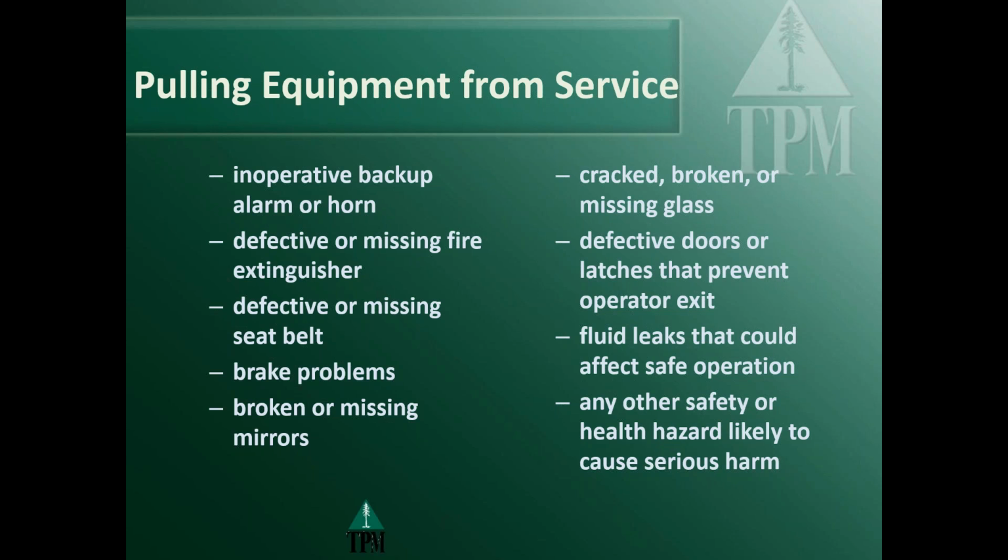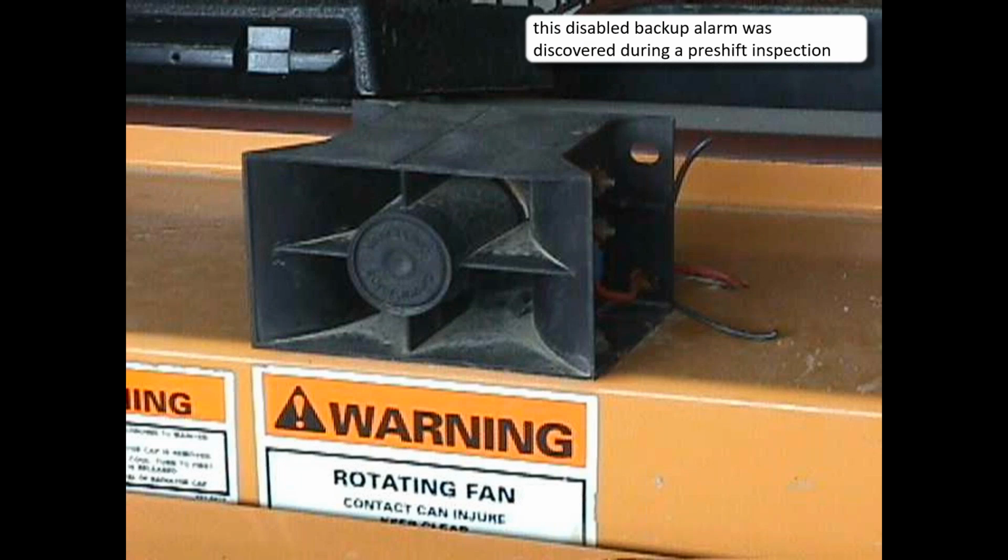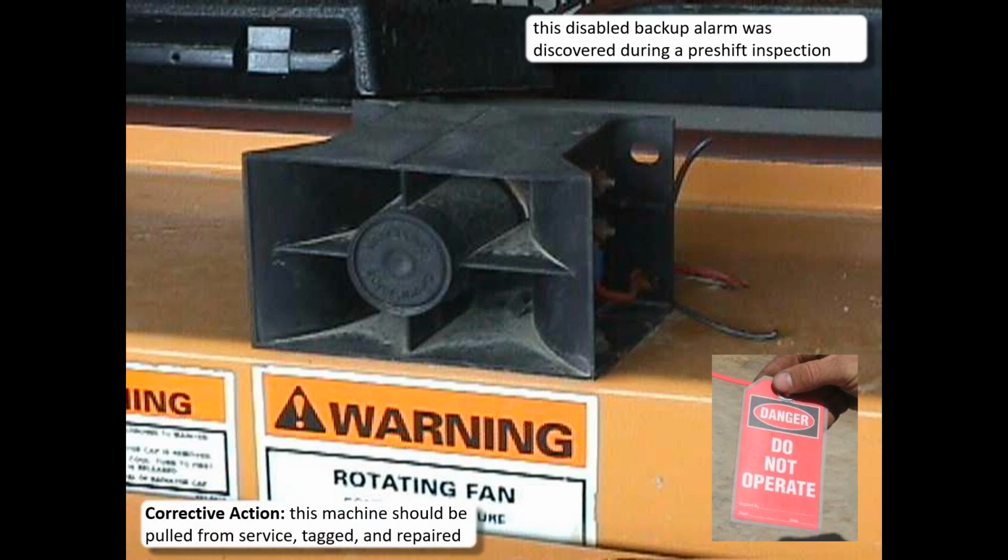That first line, from the backup alarm to the mirrors, you absolutely, as per the standard, have got to pull that machine out of service. This is an almost brand new piece of equipment at one of my accounts, and the very first thing we did to it was cut the backup alarm. If the manufacturer put it on there, it has to be functional. Like I said, this piece of equipment wasn't even a week old. So yeah, we had to repair it, and people had to get used to hearing the backup alarm. But they're required. It's not an optional piece of equipment.